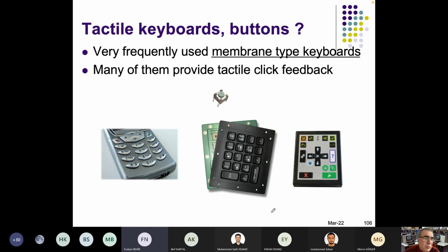So in order to prevent those kind of mistakes, for example, key repetition rate must be very long in medical devices. Otherwise, people may accidentally enter multiple letters of the same kind, because they don't check the value on screen.